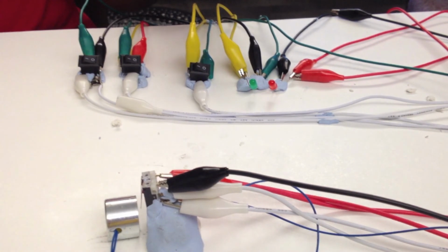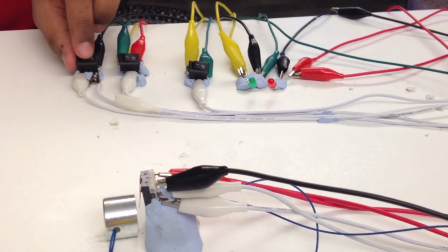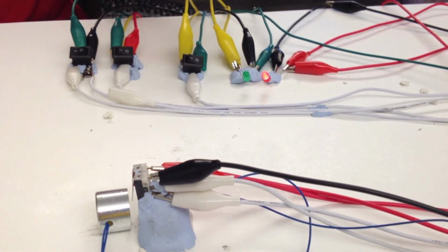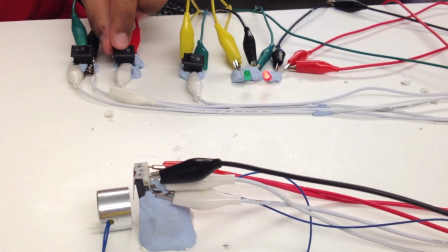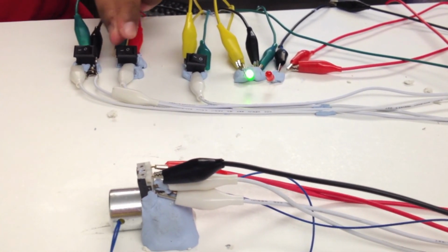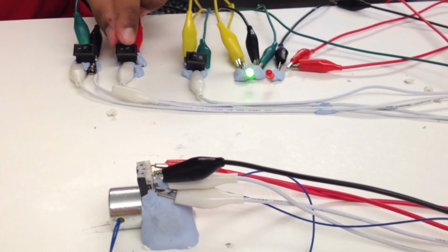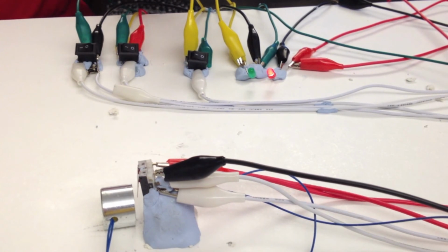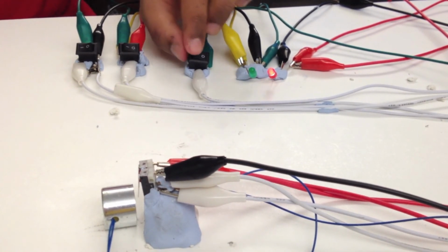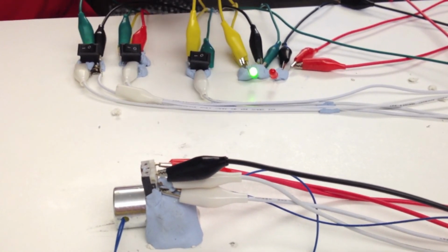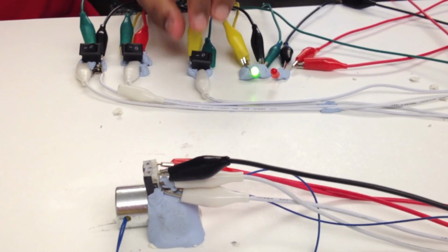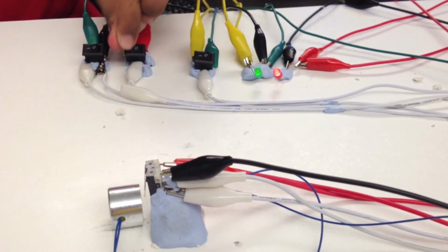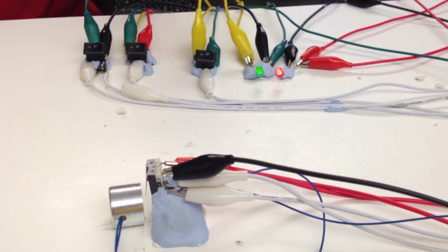Next, the carry-in bit is set to 1. An input of 1 0 0 has a sum of 1 and the sum LED is on. An input of 1 1 0 as well as an input of 1 0 1 has a sum of 2 or 1 0 shown by the carry LED as on and the sum LED as off. When the input is 1 1 1, the sum is 3 or 1 1 in binary shown by both the carry LED and the sum LED as on.